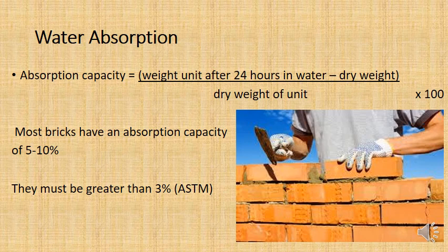It would just be like having two smooth glass blocks. You can't stick them together with concrete. Concrete needs to have some porosity in order for it to stick two objects together. And so the standard that is used in America is that clay oven bricks need to have a porosity of greater than 3%. Lower than 3%, and the mortar just won't stick to them.